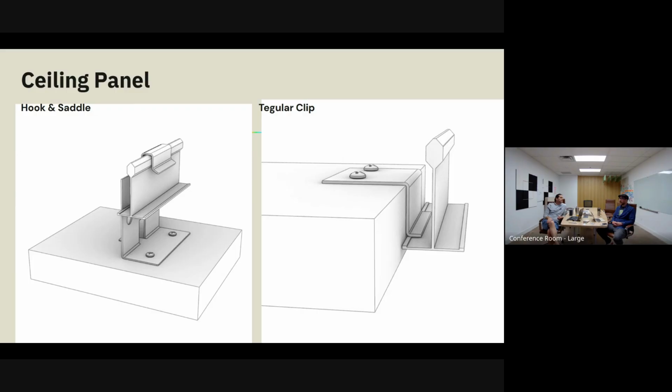And T-grid to the naked eye looks very true and square. It's not. When you put it up there, it definitely skews in different directions, especially for larger floor plans, ceiling plans, things like that too. That's why we have to have that tolerance in there.